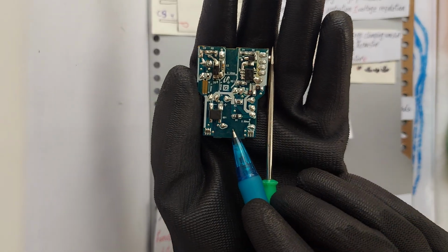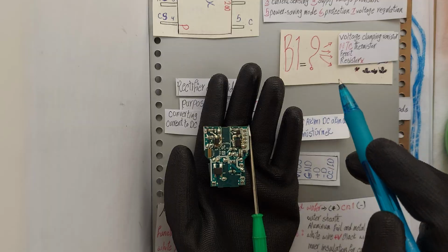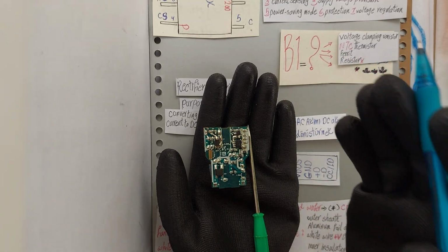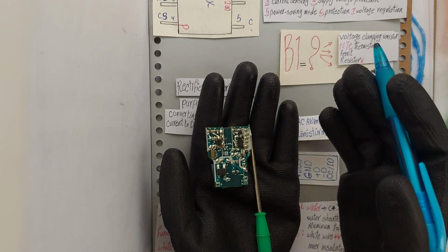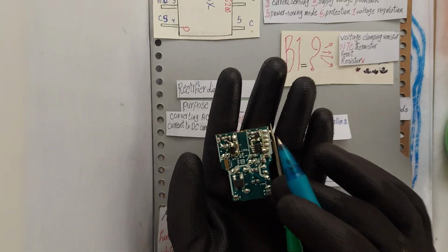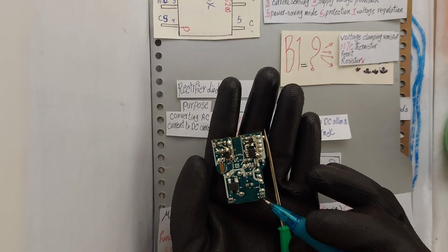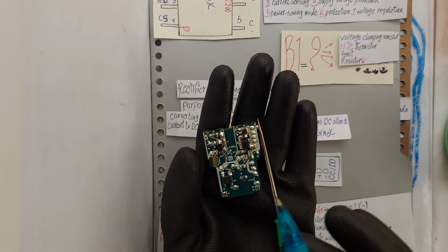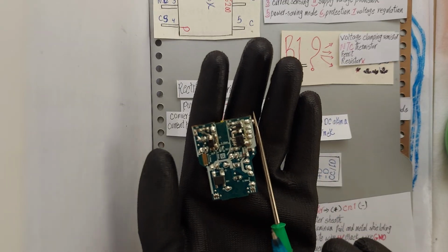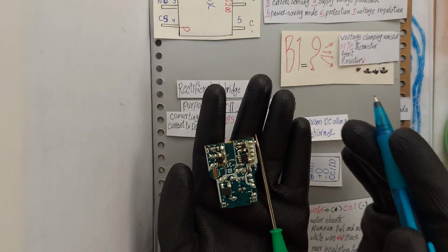As you can see here. Okay. On printed circuit boards, the label B1 typically isn't an abbreviation for something specific, but it can have different meanings depending on its position and shape. In this board, as you can see, B1 is located near a bridge rectifier labeled BD1. This component is a small black SMD part that looks like a resistor, but lacks the typical resistor markings. So let's explore what B1 could be.